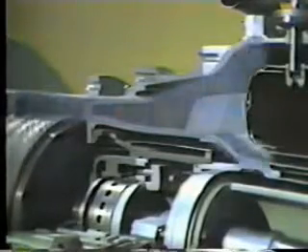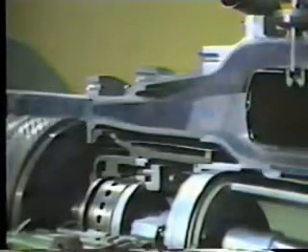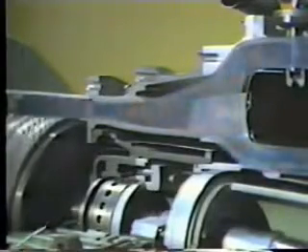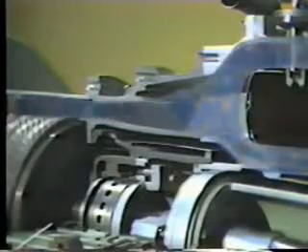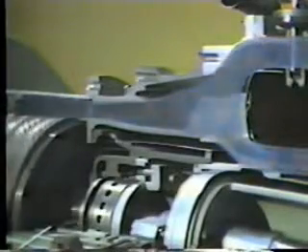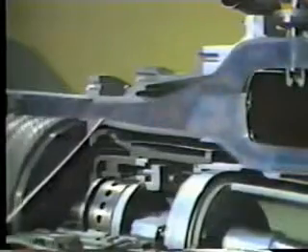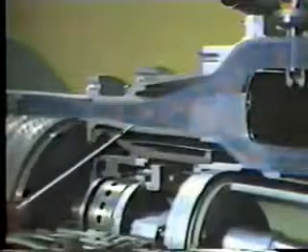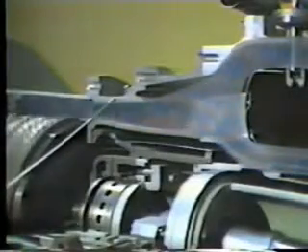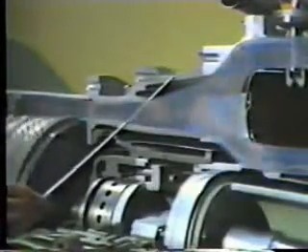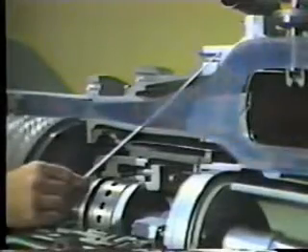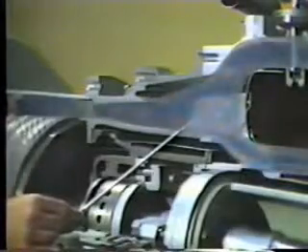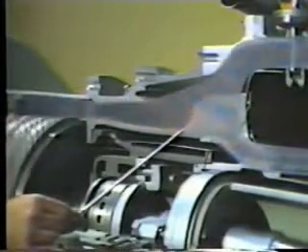As the air moves between hundreds of blades on 11 stages, its pressure is multiplied by diffusion and its velocity rises and falls in the process. After leaving the compressor, another pressure rise occurs before the air reaches the combustor. The pathway the air follows is shaped like a diffuser. The diffusion path increases in area and the air velocity slows down so combustion can occur. It is in this diffusion pathway that the final pressure increase occurs.